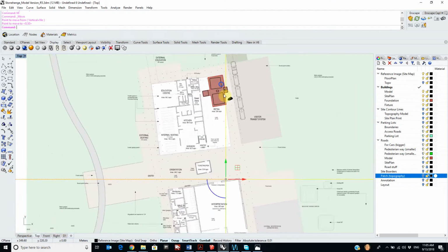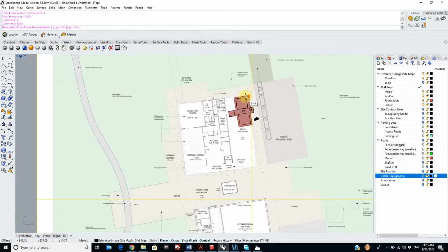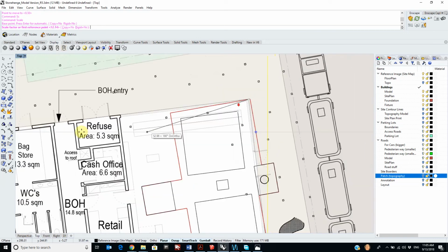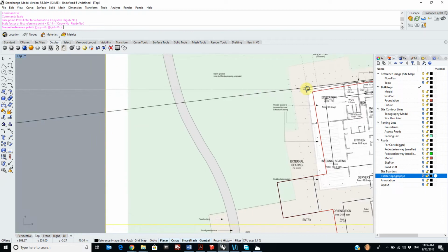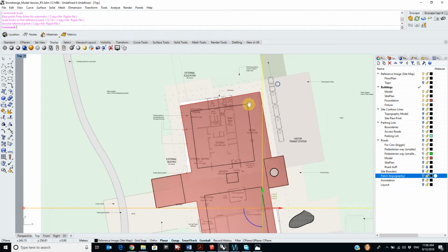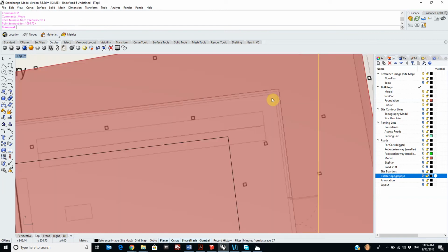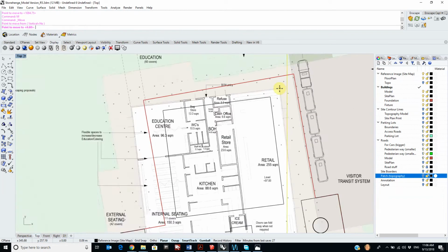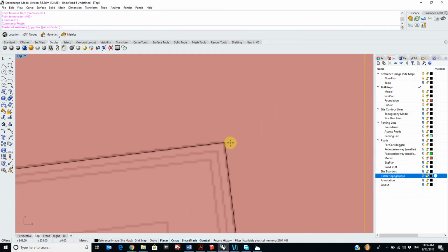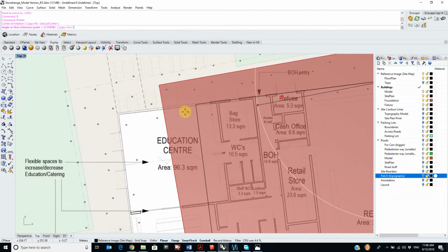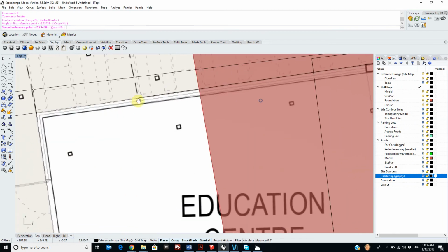So this is too big, this is not what we want. I'm gonna use a scale command to rescale the picture that I moved here. This is just eyeballing at this moment to get to a close point, and then I will zoom in to make it more accurate. Okay, I'm moving it to the lines that I previously drew, and rotate it to make sure that it is aligned with my line.